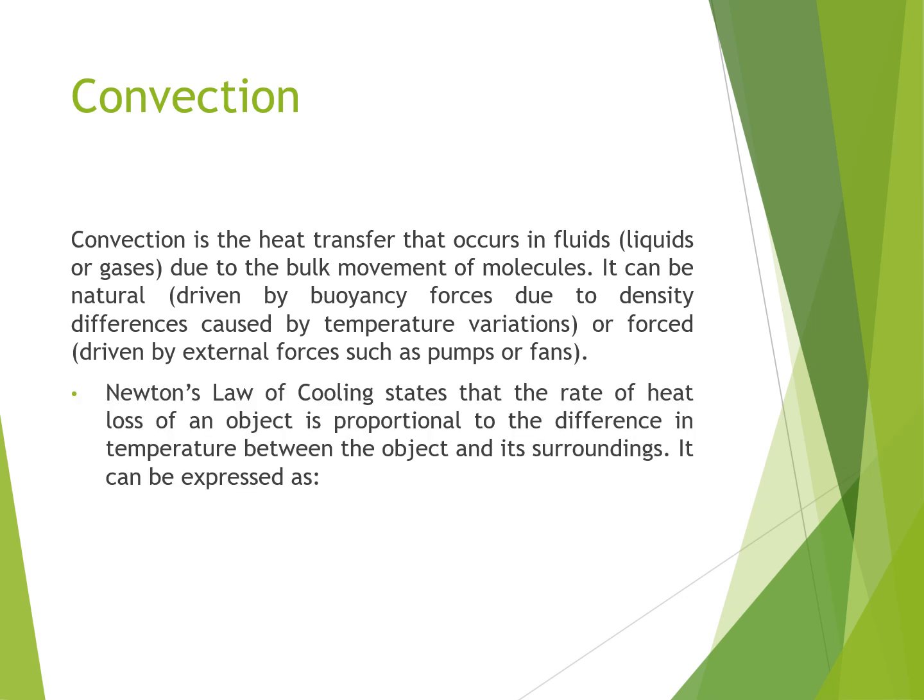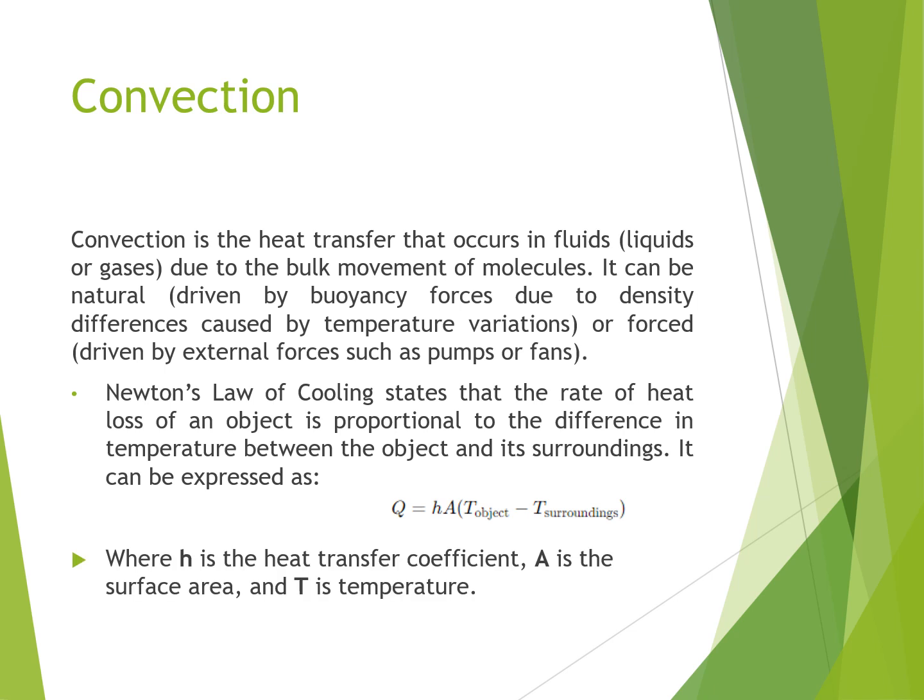So convection is governed by Newton's law of cooling, which states that the rate of heat loss of an object is directly proportional to the temperature difference between them, and it is expressed as Q equal to H A delta T, where H is the convective heat transfer coefficient, A is the area of the object, and these are the two temperature differences. The unit of H is watt per meter square Kelvin.